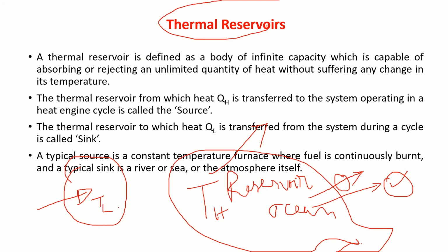Don't bring in global warming and all, sir. That's not the idea over here. The idea is that it is so huge that by pumping some heat into it or ejecting heat from an engine, its temperature increase is infinitesimally small. That is what we mean by thermal reservoirs. There is a high temperature reservoir and a low temperature reservoir. A thermal reservoir is defined as a body of infinite capacity which is capable of absorbing or rejecting an unlimited quantity of heat without suffering any change in its temperature.